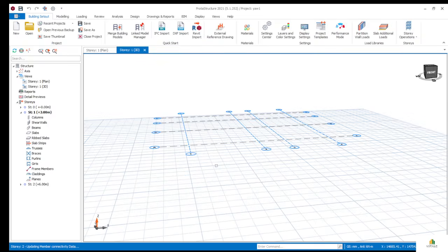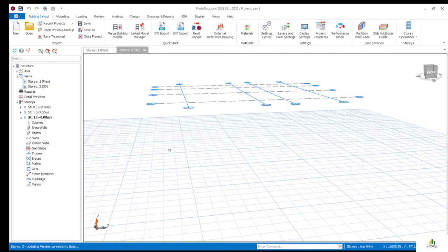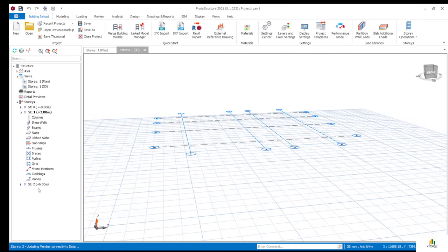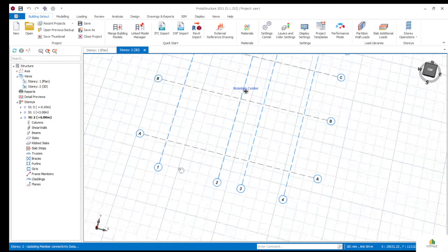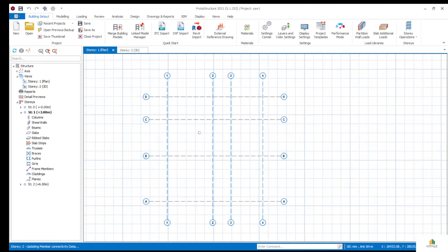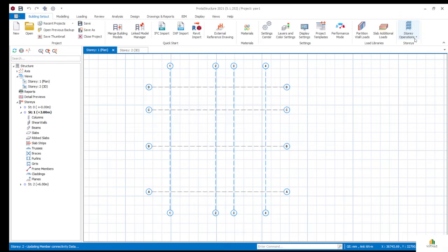So you see that these gray lines are at the story one, right? At the story one, let's say the first floor side. When you click on this side, it will move up. When you click on this side, it will move down. So the same thing, then move to this side for you to get your listing. That's how we have the insert story. So this is how you use it to generate your stories.